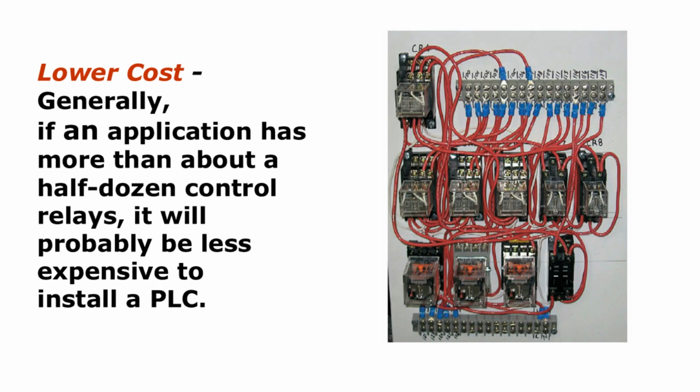The image here shows a panel full of relays. Imagine the cost of buying, wiring, and maintaining all of this. Now imagine replacing it with a single PLC and a neat set of I/O connections. Far less expensive and far more efficient. So PLCs aren't just more reliable and flexible. They're also cost-saving once your system grows beyond a few relays.